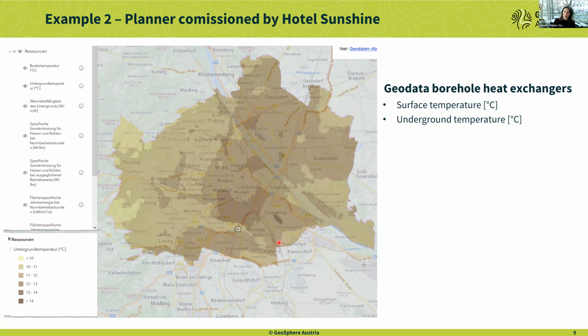So where it was possible, we used the groundwater temperature, and additionally, we included temperature profiles that were taken during thermal response tests. That were not that many, I think around 10, something like that, thermal response tests were available at this time for the city. And from that, we more or less clustered the city according to those temperature profiles and included this in the calculation for the underground temperature. So we calculated actually the mean value for example for 100 meters.